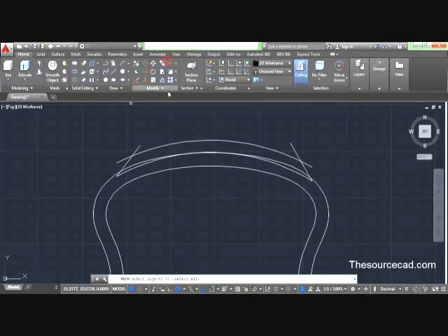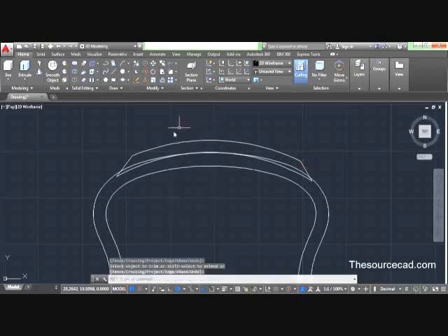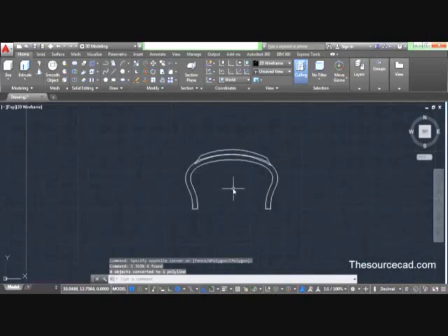Now let's go and trim all the remaining portions which we don't require. So select trim and remaining portions. We need to just trim it off. Yeah, chop them off. Now completely select this geometry, click J and enter. So here we have a completely closed profile.